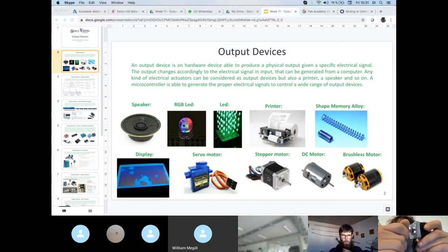This means that you have 1.8 degrees in 360 degrees, so every step rotates the shaft 1.8 degrees. According to the number of steps that you send from the microcontroller, like the command, okay, make 500 steps, 200 steps, and so on, you can move or rotate something precisely.